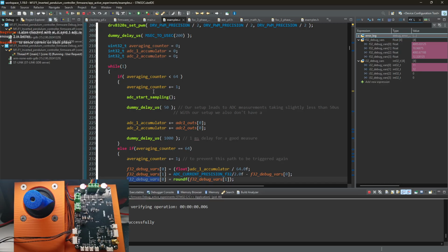You need 1 ADC per phase, and in the perfect scenario, another one for everything else, like voltage measurement, temperature measurement, or multiple temperature measurements if you have multiple of them. And the issue with your suggestion yesterday, where we can just pick a more beefy MCU and place it instead of the current one, is that it just will not work with how the PCB is currently designed.